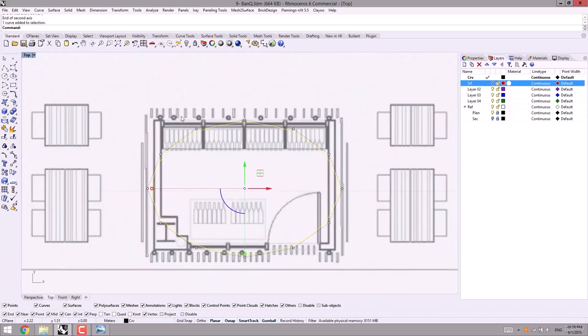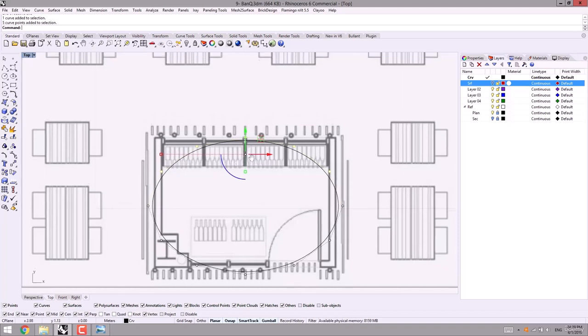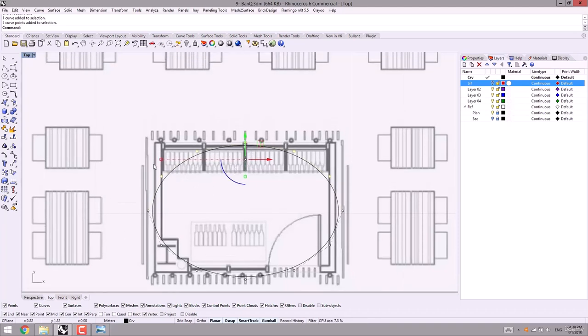Following that, I want to make the control points aligned, so we can select them, and then you can use the set point command, by which you can align the specified objects in the specified direction. For example, I select these points, and then here I can specify a specific direction or axis, and make the selected control points aligned on the specified axis.